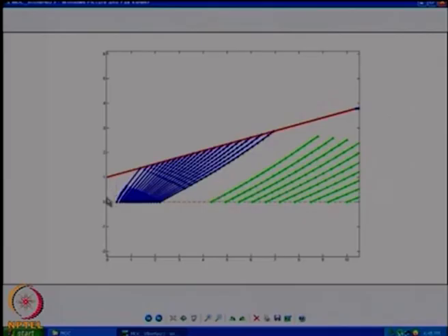If I had drawn that, then you will find that this set of characteristics are right running characteristics. If I wanted to continue with right running characteristics, they will all be just running like this, parallel, parallel, parallel, all the way up to there. That's what it will be. And if I wanted to turn it to left running characteristics, say I had right running characteristics all the way here, and I wanted to turn it to all left running characteristics, I had to create this triangular patch here. At the end of it, I will have all lines this way. After that, I can continue along this way. In any case, if I want to go from one family of characteristics to the other family of characteristics, I need to have this triangular patch.